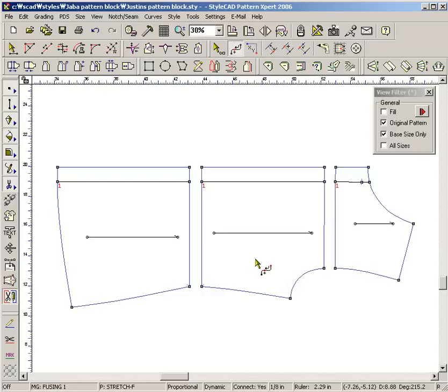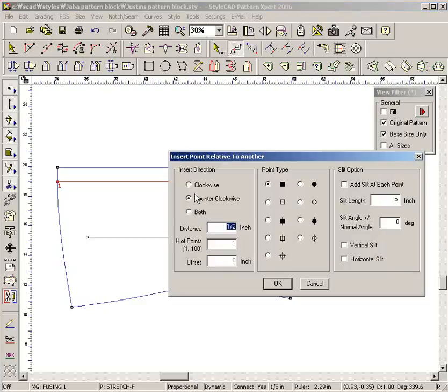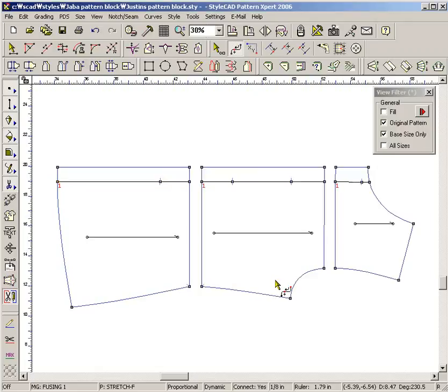The same operation can be performed over multiple disconnected sections. Select them all with the Shift key down. Click one of the selected lines close to the reference point. Enter the distance of 4 and ask for 3 notch points to add. The result is as if the 3 sections were connected as one section.